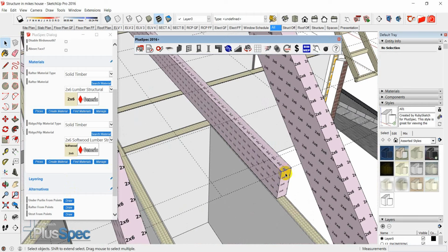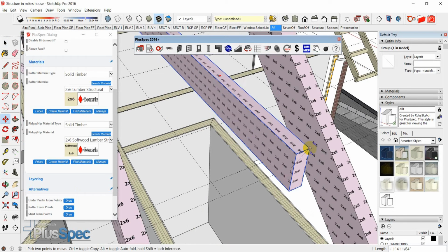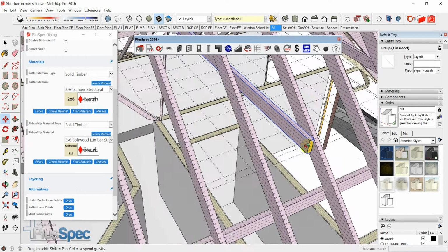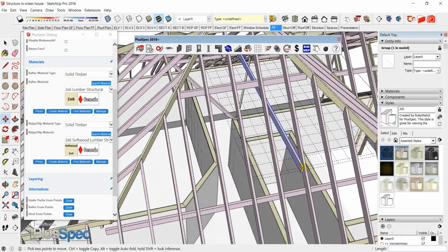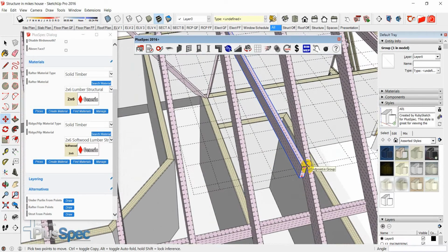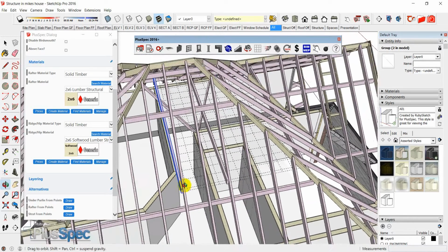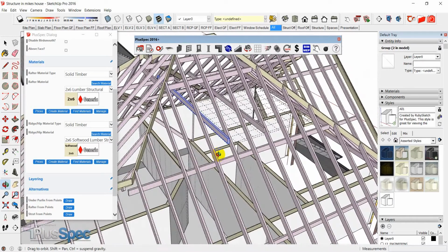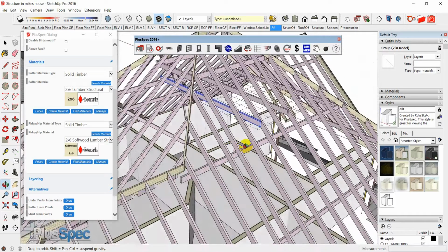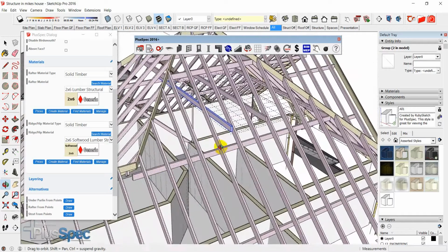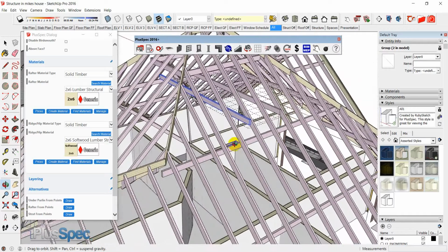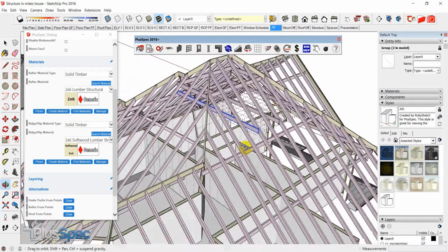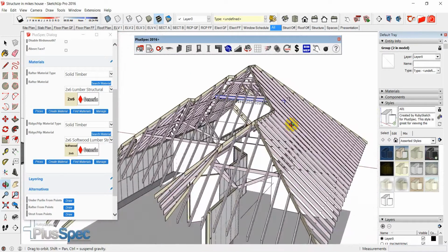Right, obviously I need to move that up a touch. And I can move those beams around to suit themselves, and I can create an array, so if we need one every second rafter, looking for my axes, and I could write in ×2 or ×3 or whatever it is, and I can put my collar ties in there. So a lot of this, the tools are available for you, it's just a matter of making sure that they're in the right locations to suit yourself. Okay, and therefore I can get a very detailed roof.